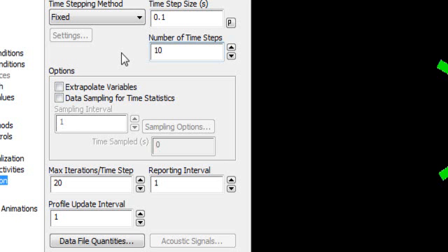So that means if you have a very small time step, you can resolve the solution at a very slow speed. When you have a very highly turbulent flow, you have to capture all of the turbulent properties, so you need to proceed your solution very slowly. So you need to put your time step at a very small number. But when you have a low turbulent flow, then you can increase your time step.